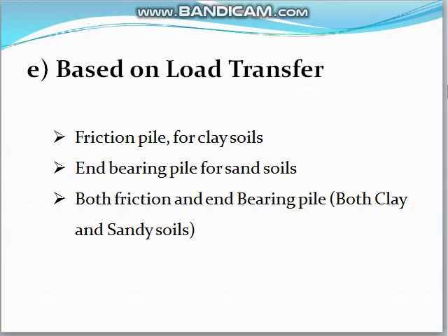Displacement pile means the pile causes lateral displacement. Example, all driven piles. In non-displacement pile, no lateral displacement of soil takes place. Example, bored piles.